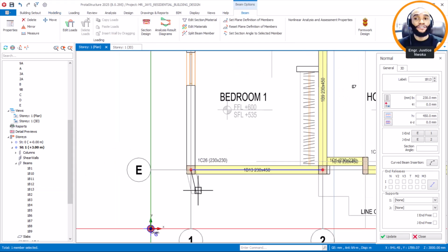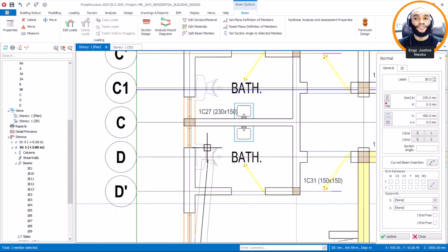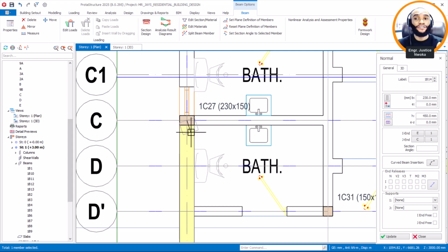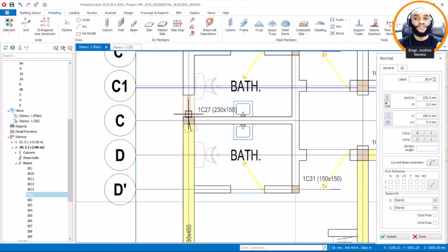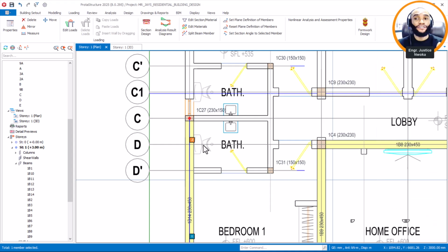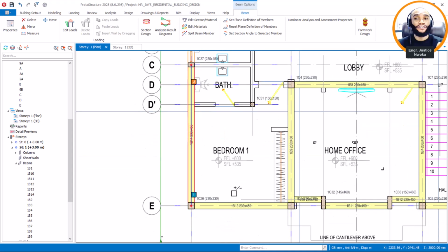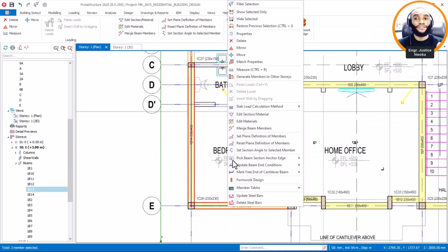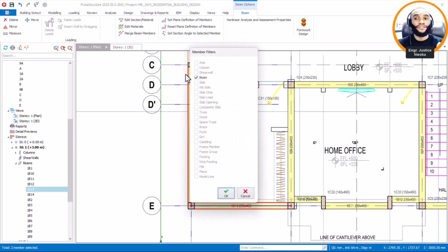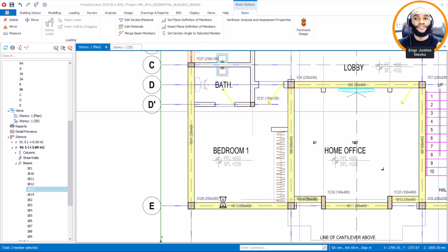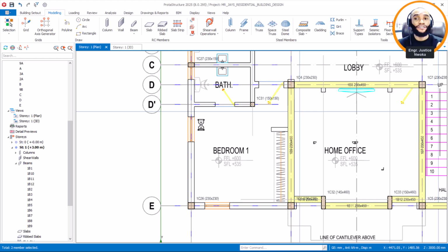That's fine. So we then come again now and keep this here. Now, sorry, we will not have to put this beam depth here because this place is a bungalow. So with that, I'll just remove this other side, right click here and then say delete. We are going to specify a different beam depth here because this is just a bungalow carrying just the roof.